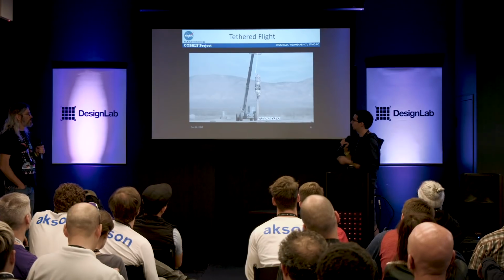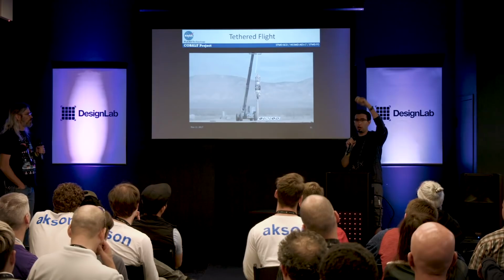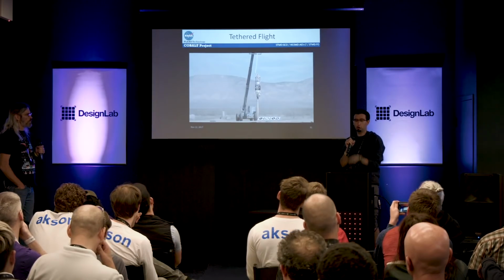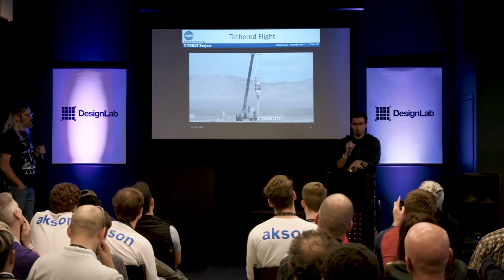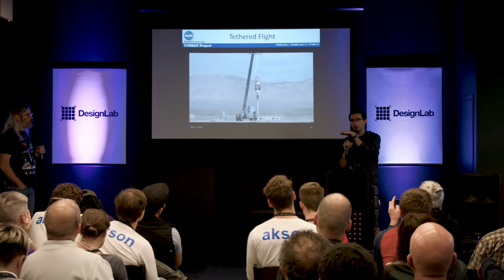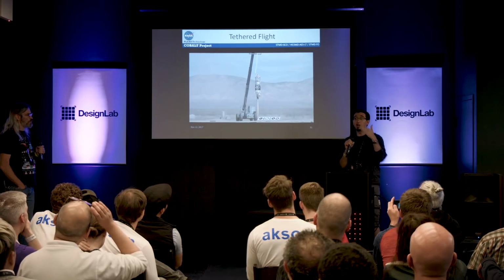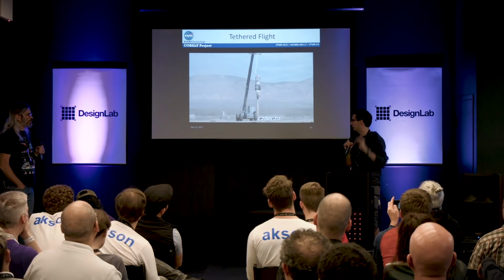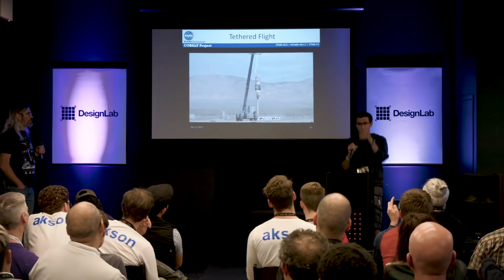So what we did first was a tethered test where we put the rocket on a crane and essentially do a short hover. So we initialize our system, look at the targets, take off, hover a couple meters above the ground, move to the left, move to the right, do a full flight duration of a minute and a half or whatever it was, and then come back to center and plop down.